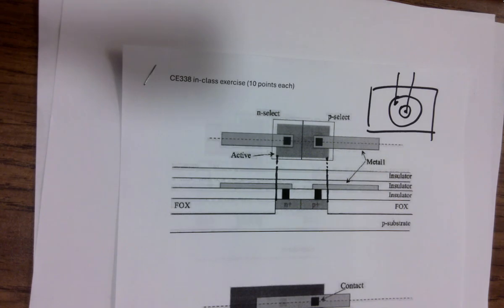But still, I mean, which one should go first? That's a good question. I guess it depends on what you need more concentration later on, because you're gonna have to overdope, because it's probably gonna leak into one side. You're gonna have to account for that gradient. Or what I'm thinking is if you dope an N plus material in the P plus area, it's gonna start to neutralize it first, and then it goes to the other direction. You know what I mean? Is that possible?